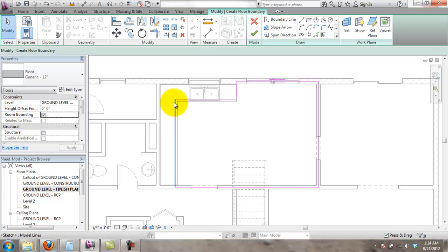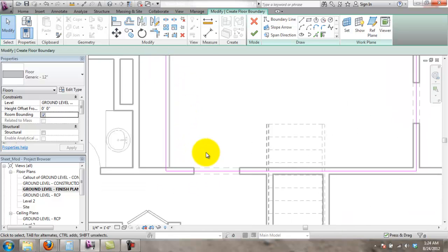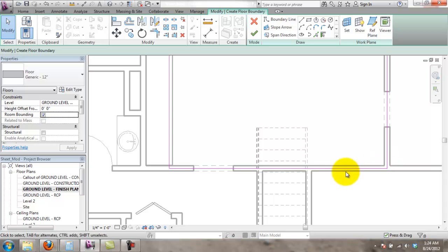Now you would need some kind of subfloor ultimately if this was more structural. It's not a structural drawing, so we're not really worried about how the floor is actually constructed. We're only worried about pretty much a visual representation of what this is going to look like. And to that extent, thinking ahead, if we do end up doing a hatch, we don't want the hatch to show up under the doors.